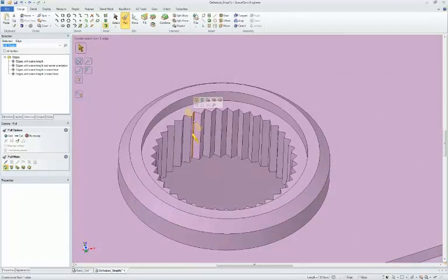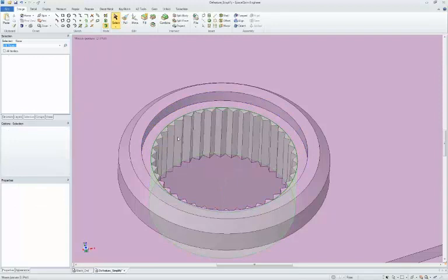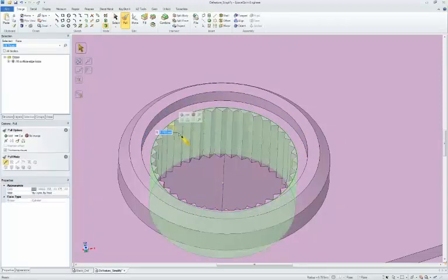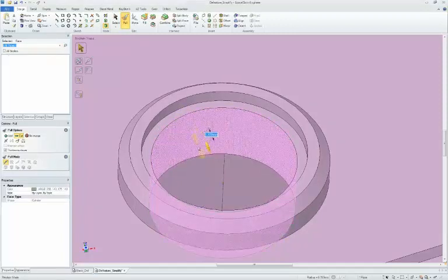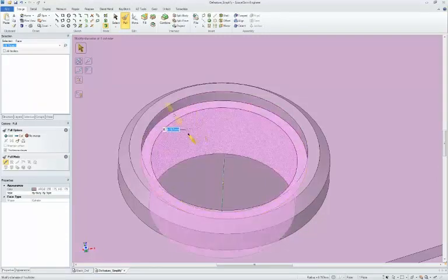To us, it's all about giving you easy ways to, first of all, remove geometry, but also create geometry. If I want to pull that to create a surface to cut with, I can revolve that edge around the axis, giving me a surface that's there. And if I want to just cut with that, pull adds geometry, pull cuts geometry away. Or I could have used our split solid tool to slice it away. Or I could have sketched my own circle.